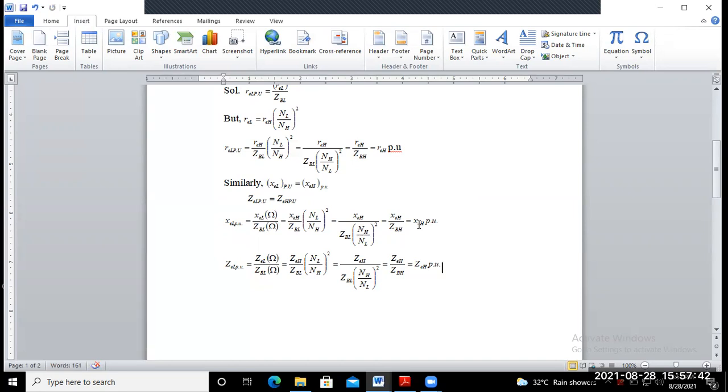What we considered here is just the transformer part. In an actual power system, we find other components of electrical equipment: transformer, generating power alternator, transmission line. Here you have to be careful about the base voltage and base impedance.